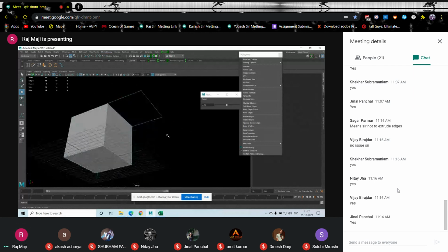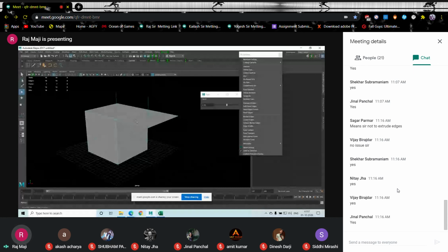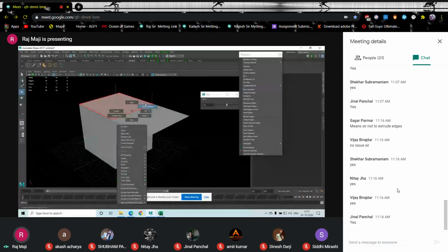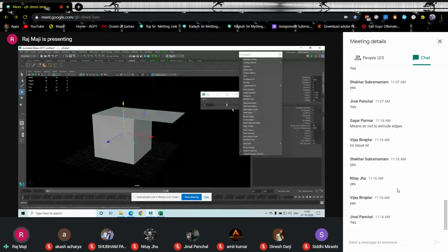If somewhere you can see a black patch, now you know what to do. You need to come to mesh display and reverse it. First, you check if the normal is incorrect. In most cases, the normal will be incorrect, so there is no problem. You select the face and reverse it, so you are correcting the normal. Now, if you don't want to see the normal, just select in object mode and face normal. So it is there, but it is not visible anymore in the viewport.